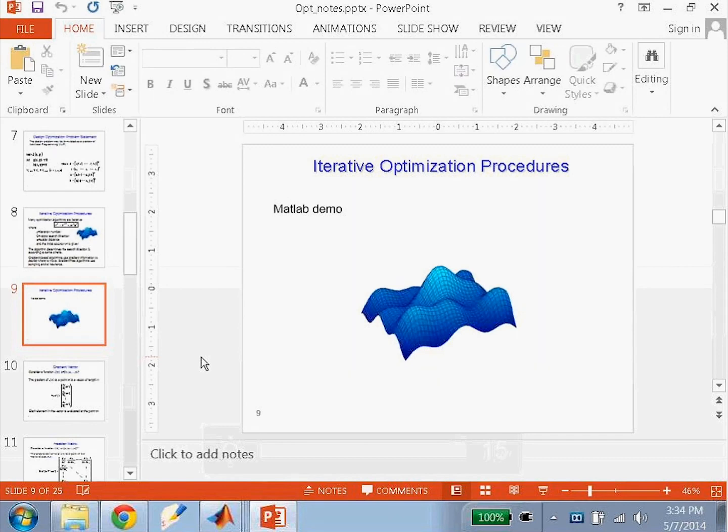Yeah, so we're going to talk about that. That's sort of number 3. J is usually going to be computer code that we can put the shape of the aircraft wing or the whole aircraft into, and out comes range or cost or whatever it is. So we can usually only get at J of X through simulation, not necessarily analytically. And so we're going to need some way to compute gradients. What's really nice is finite differences, which you saw a few months ago, and that is what we're going to use to do that.